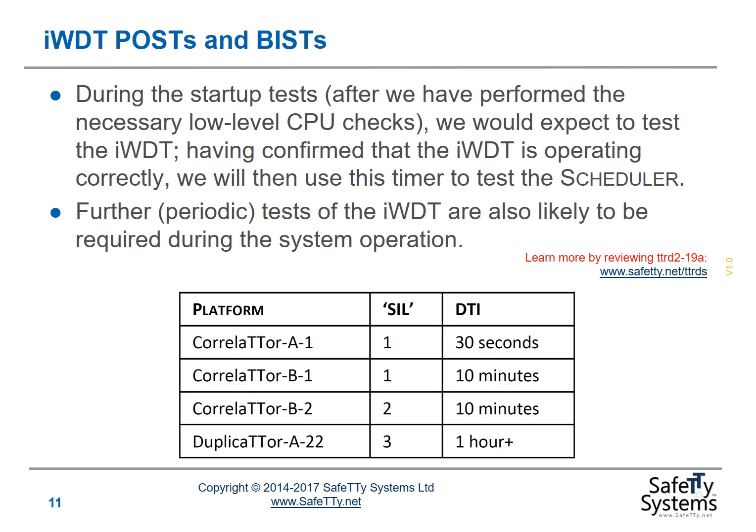The key point to note from this slide is that if we're using a watchdog timer, we need to consider what POSTs will be performed to ensure that the watchdog timer is working correctly, and we need to consider what built-in self-testing may be required to ensure during the system operation that the watchdog timer is still operating correctly.